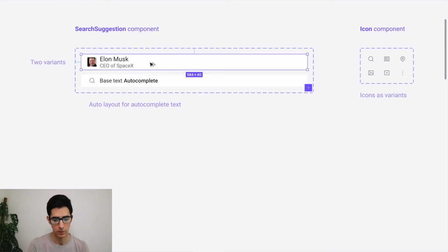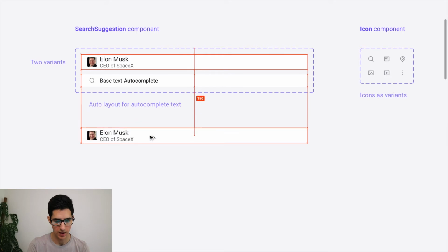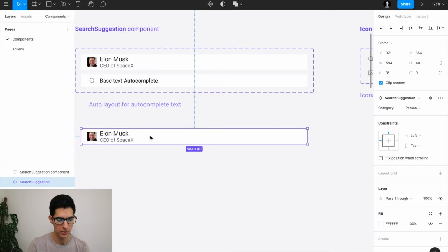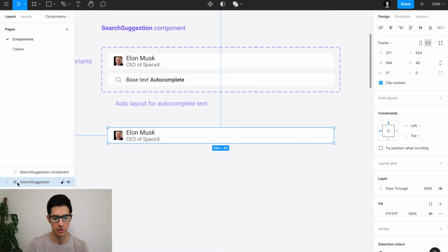But for this tutorial, I'm just gonna duplicate it by holding my Alt key and then dragging down here until it becomes visible. I'm gonna bring back my Figma controls by holding my Command key and then pressing the period key, and that will bring back all of these. And what I'm gonna do is detach this doing Command Alt B. So that is how you can detach an instance of a main component from the component itself.